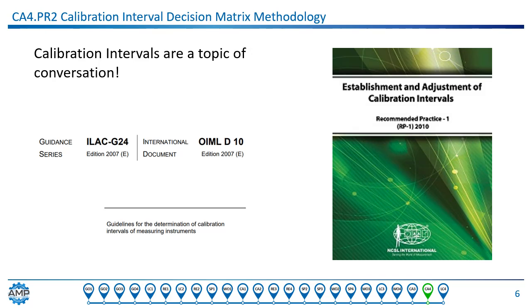So the short version is that intervals can be established by using complicated statistical models or by review of pooled or published data about the same or similar instruments, or by starting with OEM recommendations. The decision about intervals should be made by a person or by persons with general experience of measurements or of the instruments to be calibrated, and preferably who also have knowledge of the intervals used by other laboratories or facilities. An estimate should be made for each instrument or group of instruments as to the length of time the instrument is likely to remain within tolerance after calibration.